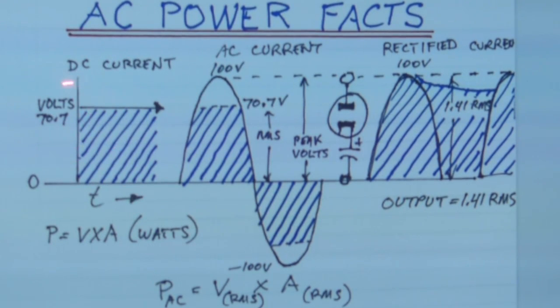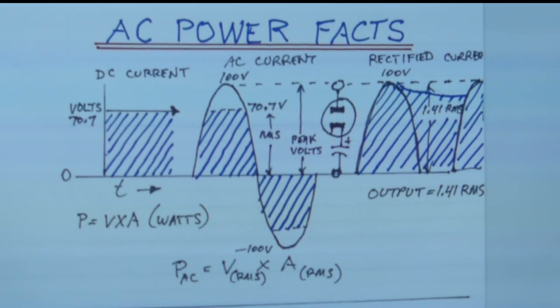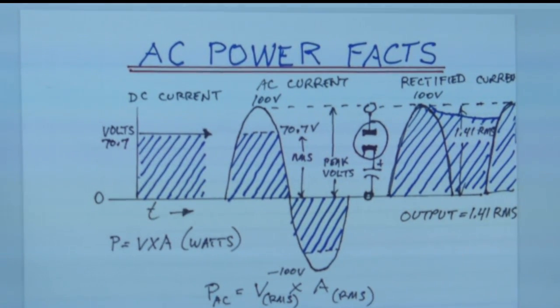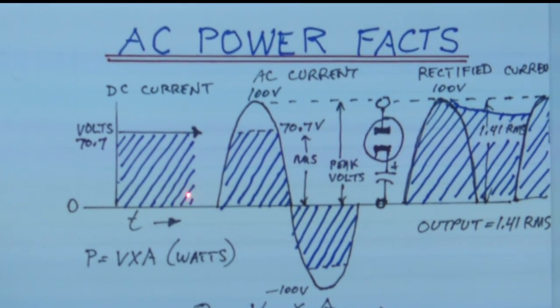Now where we get the RMS in is that if we were to take a number of little samples, just think of a number of little vertical lines going up and down, right up to the tip and then down again, and the more samples you have, the better. With each sample, you'll register a voltage. This one here would be very low, this one would be 100 volts, and that's an instantaneous value, not an RMS or a peak value. That's an instantaneous measurement.